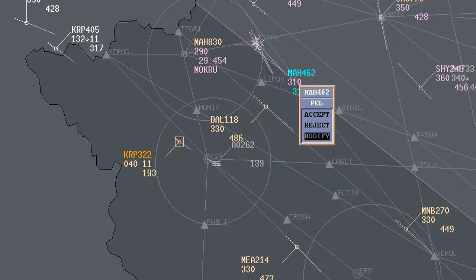The information available to a controller from radar-derived sources will, as a minimum, include continuously updated radar position indications, radar map information, SSR returns in Mode A, a simple acknowledgement return, Mode C, an acknowledgement return with height information, and the new Mode S return, which will encode a unique identifier.